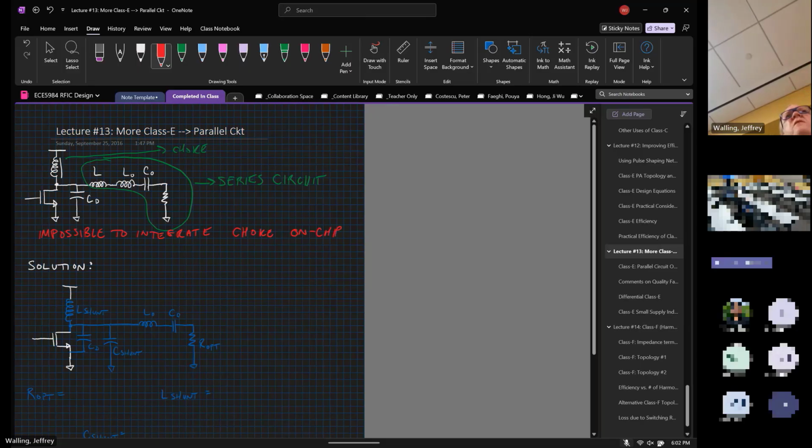How many of you have been playing around with the 22 nanometer PDK? What's the largest inductance that you found that works at a few... 6 or 8? Yeah, something in that ballpark. And then you're going to have a fairly low self-resonant frequency when you get that inductor.